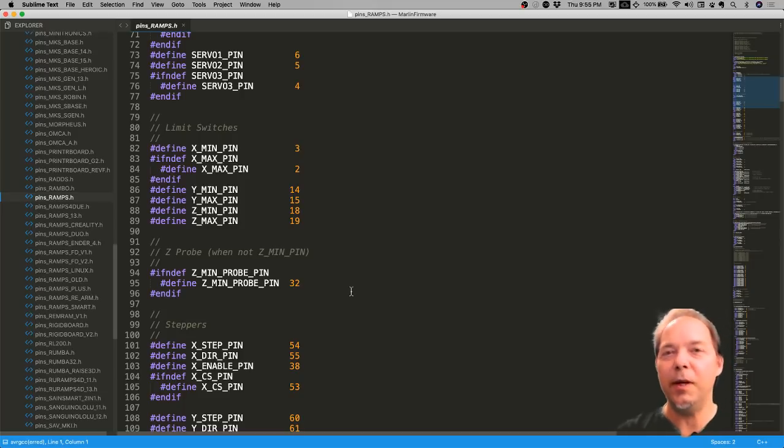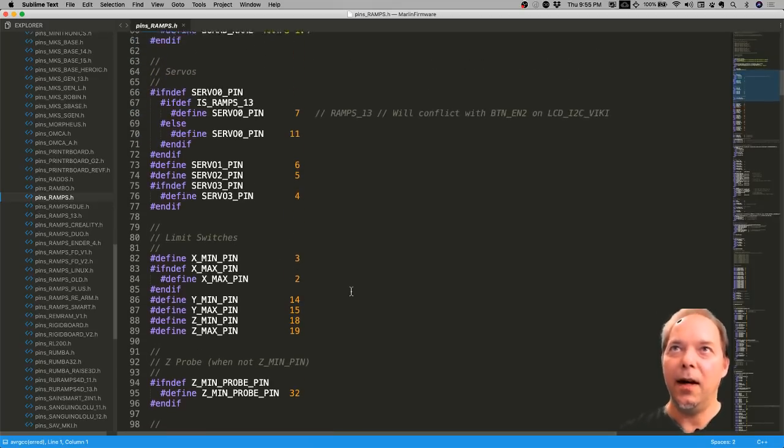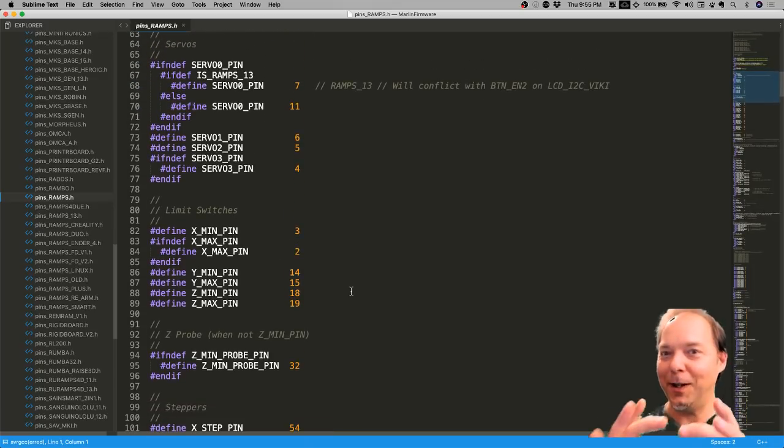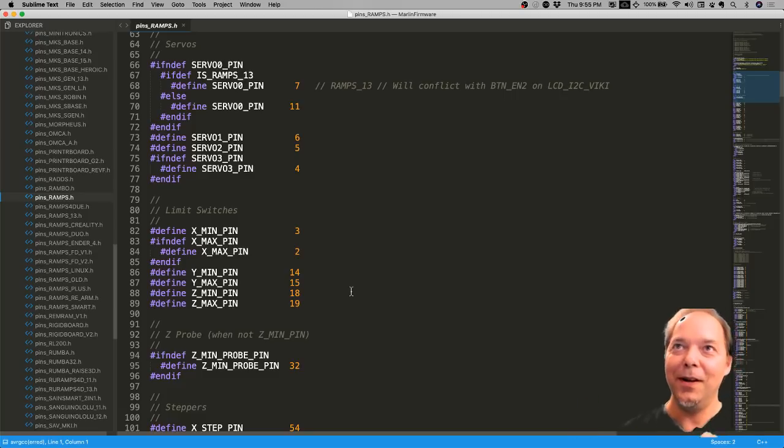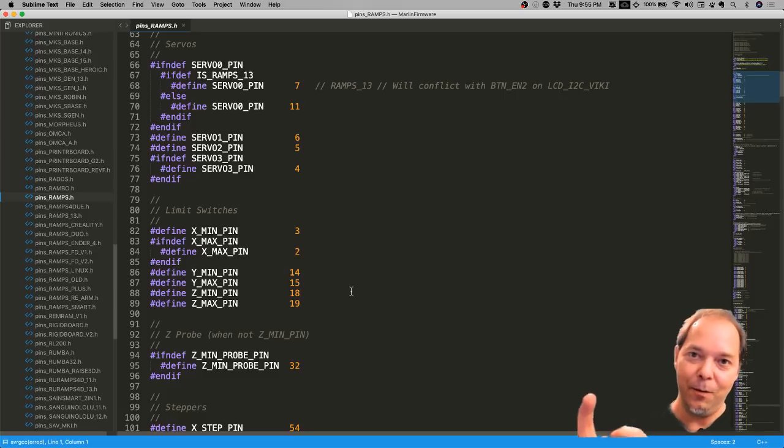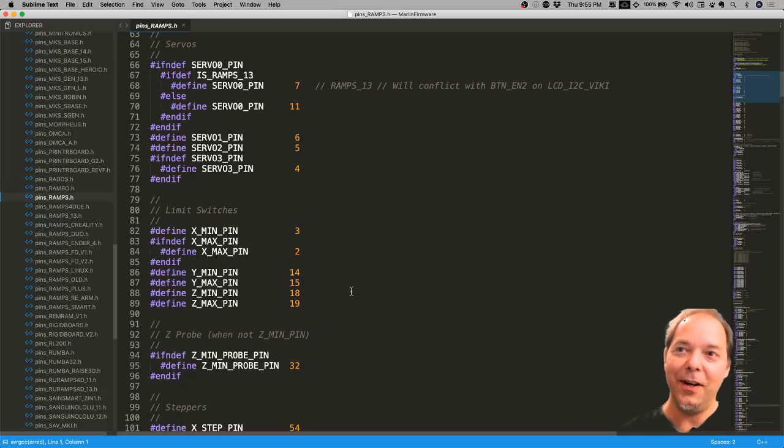So it'll be like port B, pin 3, or something like that, which doesn't mean the port on the board. When you're looking at the board, it'll say like aux 3 or something. It actually means the chip itself has pins defined in terms of little groupings, and each grouping is called a port, and that port has maybe 8 pins on it, which maybe correspond to bits on that port. And so that's kind of how ports and pins work. And so you could look at these ramps pins, which are numbered as integers, as being also port pin combinations, but you just don't do it that way historically. This is the way we've done it.